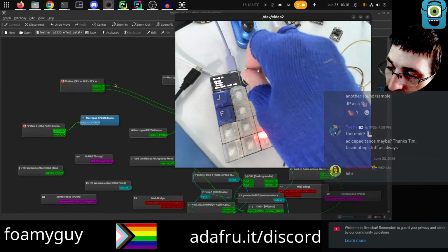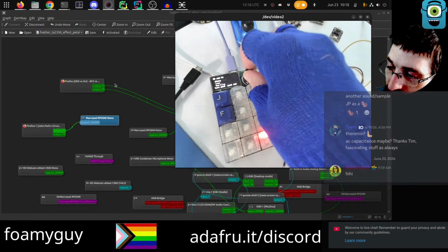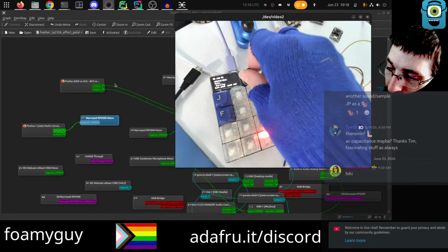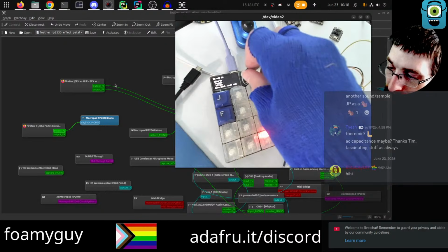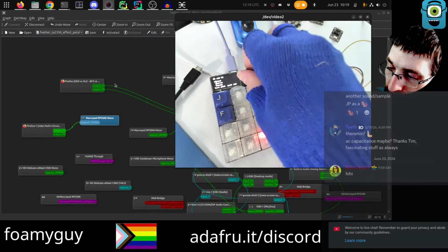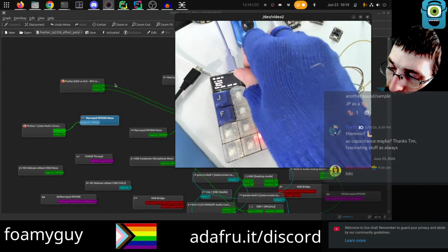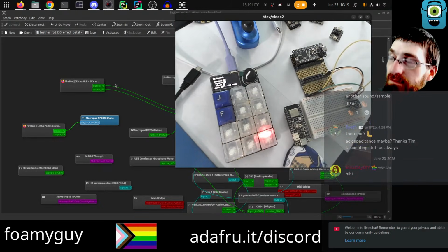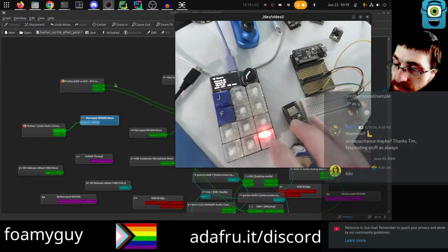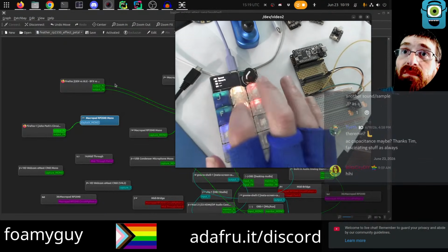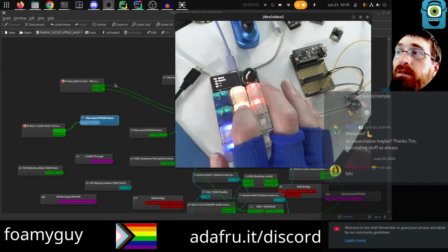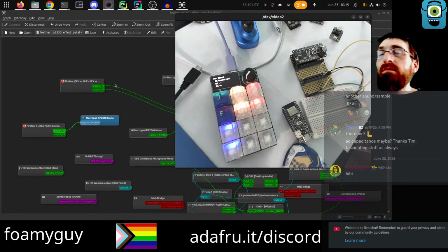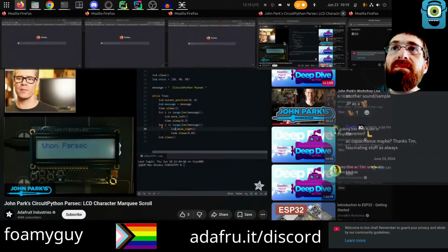And we can do a bunch of other effects as well. So I'll do one more just for fun. Move left command. That doesn't worry about individual characters. That takes the whole message that you've printed. It's on the display buffer, and then moves it to the left. And we are running that at the rate of 0.3 seconds. So that's what gives me this sort of nice moderate speed. Okay. And then on the next loop.